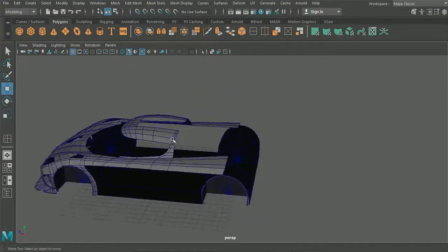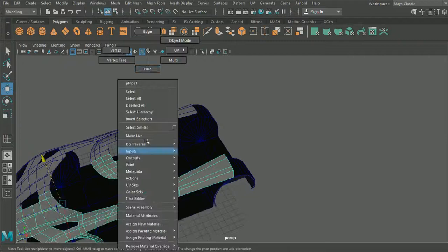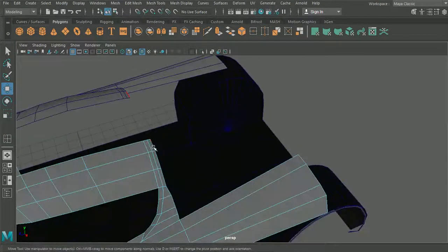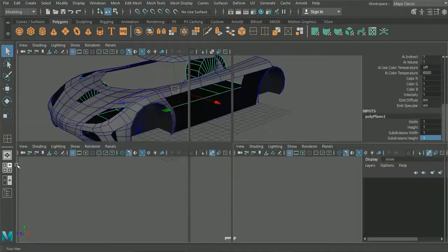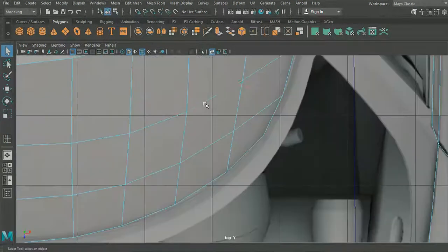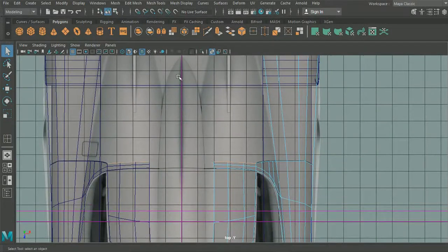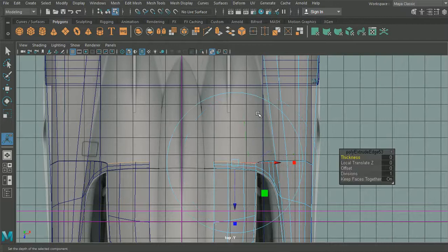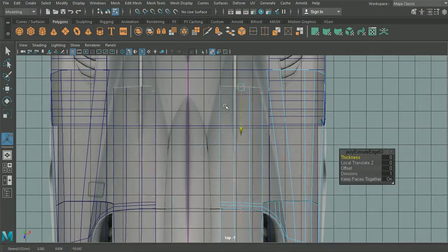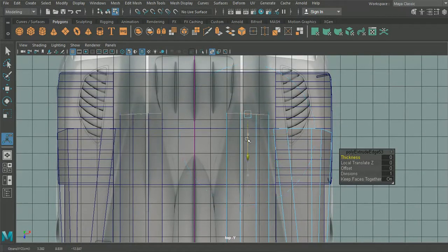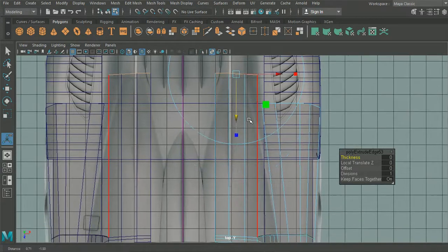So, down this rear section here, what we could do first is, I think it would be best to take a little bit of information. So we don't want to take all of this section too. So if we grab these points here and we hit Ctrl E to extrude, and what we'll do is we'll take them all the way down to this lower section here.